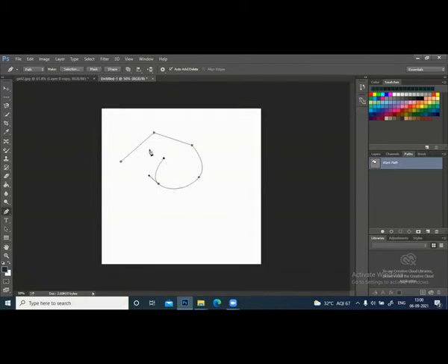You can have a straight line now. Closed. So if you want to switch this off, press escape once. It removes the anchor point. Again, if you press, it goes. So it is available in the Paths panel. So go in the path, click it here.